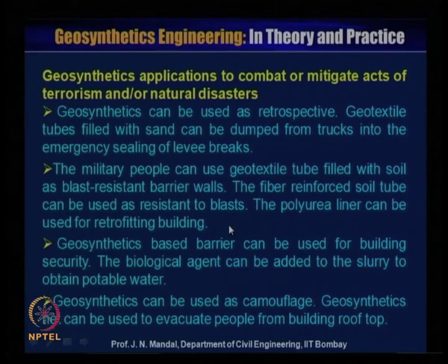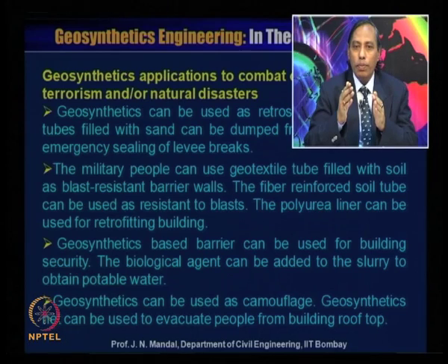Now, geosynthetic applications to combat and mitigate acts of terrorism and natural disaster. Geosynthetics can be used in a retrospective way: a geotextile tube filled with sand can be dumped from a truck for the emergency sealing of a levee break. The military can use a geotextile tube filled with soil as a blast-resistant barrier wall. A fiber-reinforced soil tube can also be used as resistance to blast.